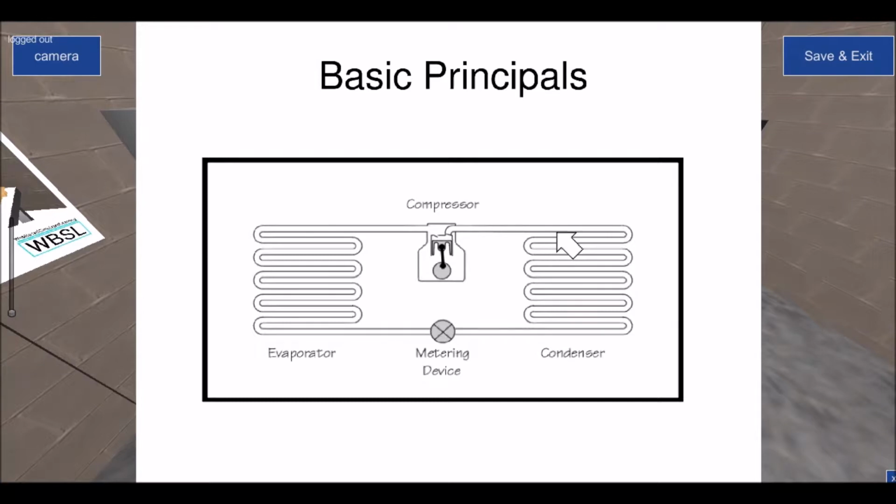The condenser, then, I call it three zones. As far as I'm concerned, there are three zones inside a condenser. There is, first of all, the desuperheating zone. What you will notice when a refrigeration technician comes to a refrigeration plant and is trying to see if everything is working accordingly, when they're testing the condenser, they will put their hand on the top of the condenser. Now this comes with a warning: the top of the condenser could be as high as 70 degrees sensible temperature. So the temperature could be too hot to touch. Be careful when you touch the top of a condenser.